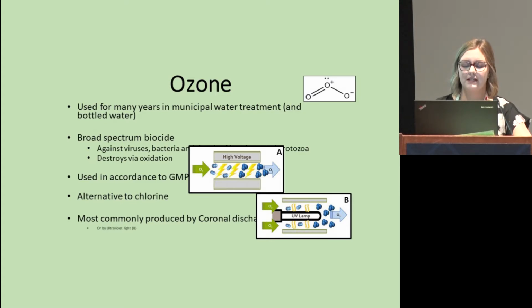The ozone produced by these methods is able to rupture cell walls of organisms, proving to be very effective. The levels permitted on food items must be in accordance with good manufacturing practices, and unlike other chemicals I've spoken about, ozone has the great advantage of not leaving residue byproducts. However, workers must be very cautious when working with ozone to prevent damage to the lungs.